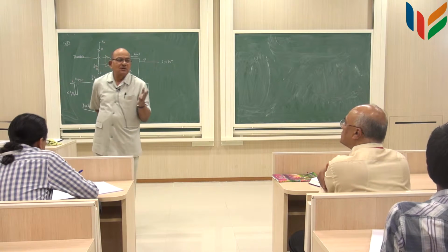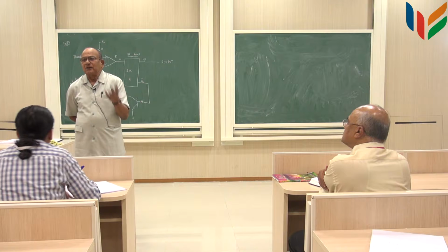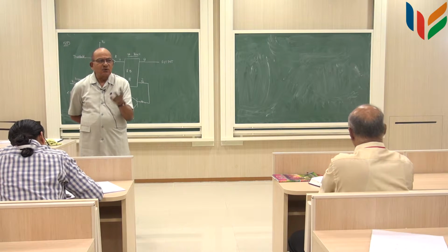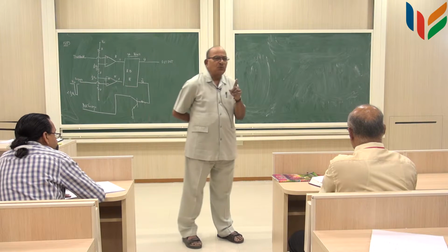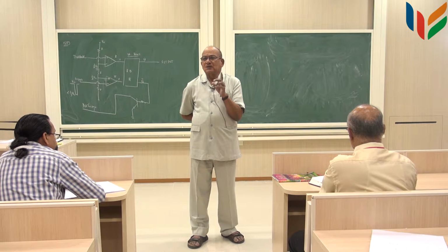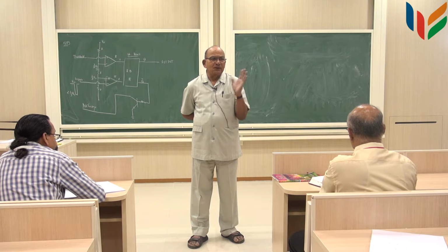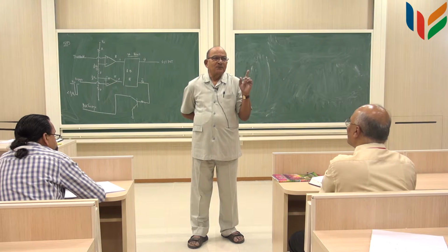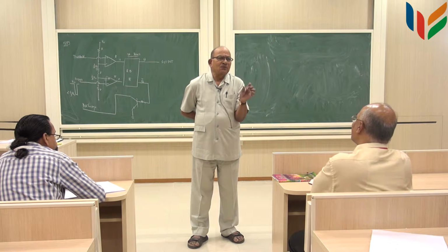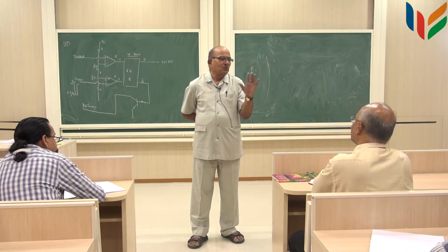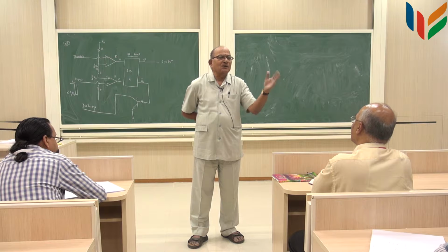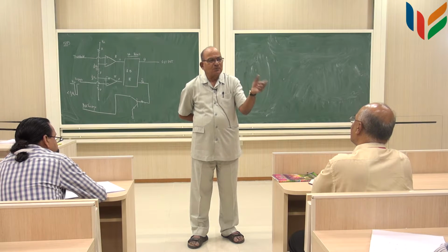But basically what you have here is a multiplication by using a diff-amp, and that we have agreed when we studied the diff-amp, we can do that. The only problem we had was that a tan hyperbolic function came in the diff-amp, and there is a simple way of converting this tan hyperbolic function to a linear function by using an inverse hyperbolic, by using a simple diode.